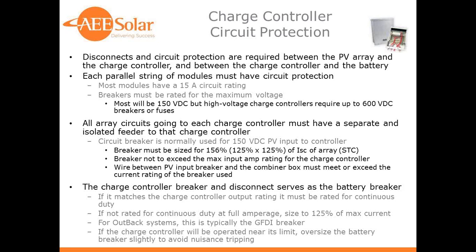Brian, can microinverters be used on an off-grid system? That's a good question. Yeah, they can be used in an AC coupled application, but the efficiencies are really low. I wouldn't recommend doing that.